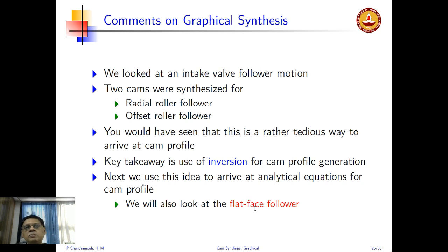So from the next lecture, we will move to the analytical methods and derive the cam profile equations, and then life is very simple. I have the cam profile equations for the roller follower and for the flat face follower, and all I have to do is plug in, put it in an Excel sheet, and generate the cam profile. Voila, you can plot it in any software that you want, and you have the cam profile. The proof of the pudding here, of course: we have done a graphical construction. So we'll revisit and see how close it came to the actual cam profile that we designed when we use the analytical method. Okay, so with this I will stop, and in the next lecture we will start with the analytical methods.